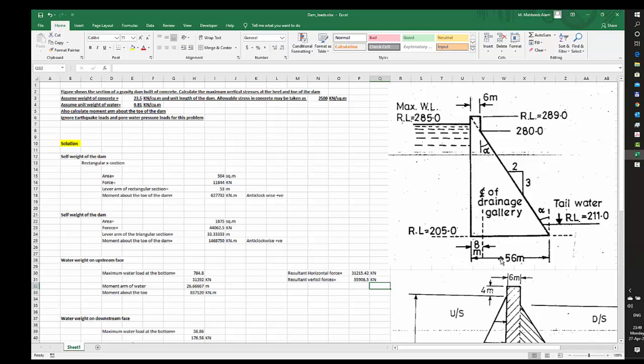And because this is also in vertical direction but acting from bottom to the top, that would be in reverse direction to the self load of the dam. So then we would have also needed to include that in the resultant vertical forces. The self load would be in downward direction, the pore water pressure in upward direction, and then we would have got the resultant vertical forces.